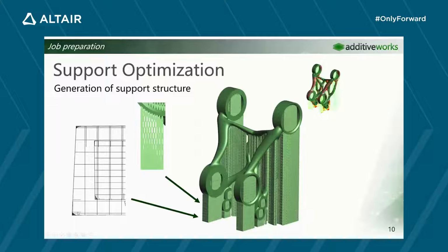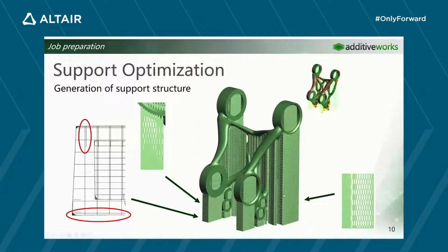We can also see on the top view that there are doubled walls, like a double thick wall in the corners, to strengthen the structure and avoid delamination. On the right-hand side, where you see the green dots, we can see that the density is at minimum, meaning we have maximum perforation, I think 70% here. Of course, this depends on the recoater and the machine, but this is saving a lot of process time. And we can also see that the interface size is changing with the geometry.